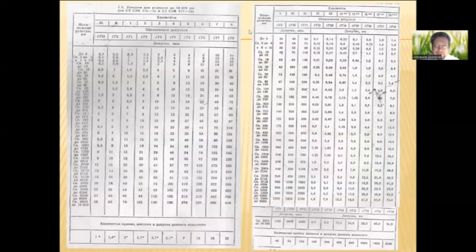In these tables, you can see the numbers of units of tolerance A. For the IT grade 01, A is equal to 1. For example, IT grade 3, A is equal to 3.7. And for example, for IT grade 14, A is equal to 400.